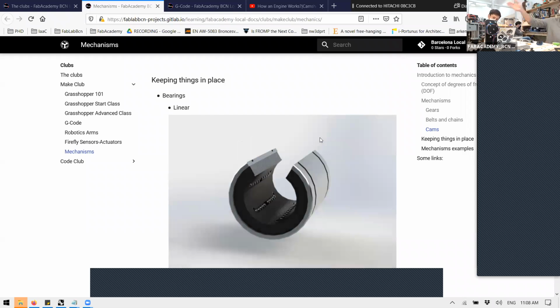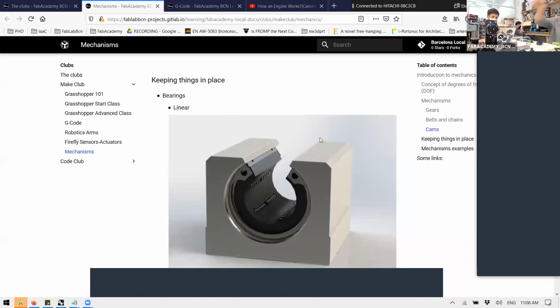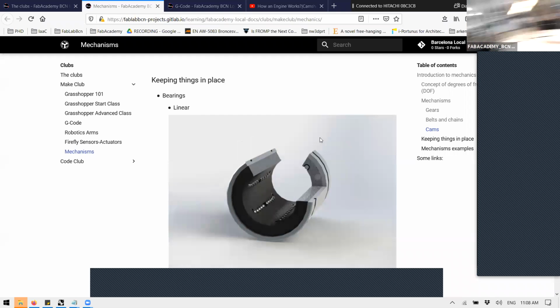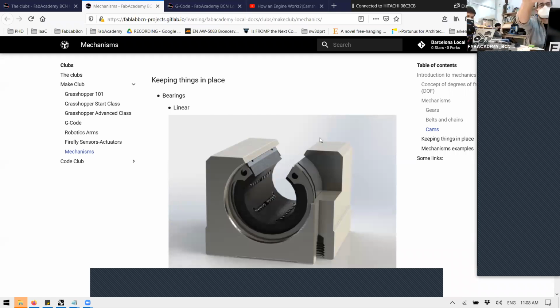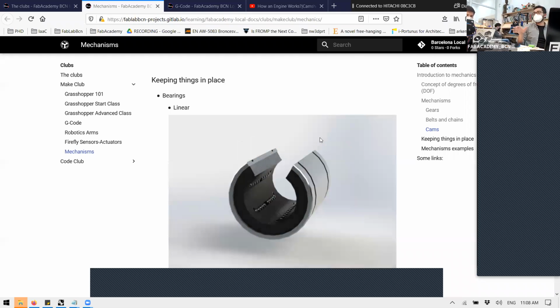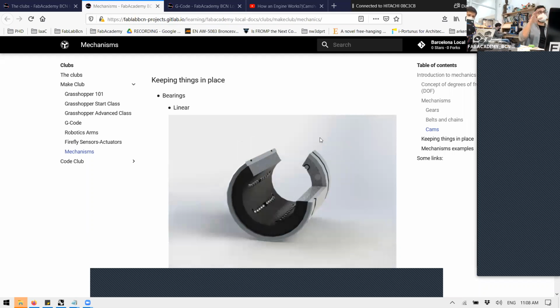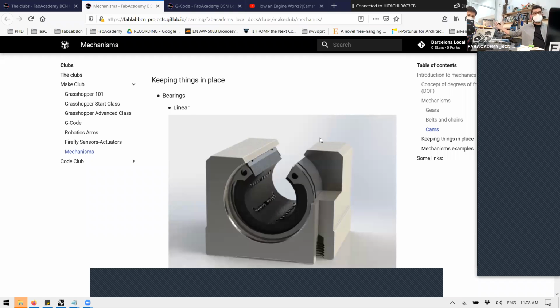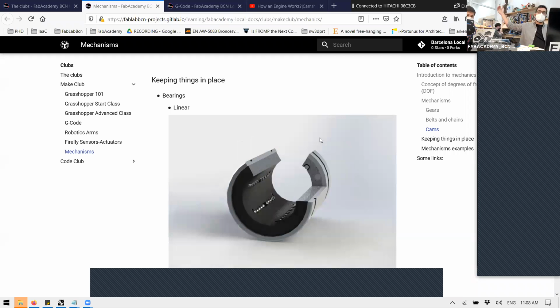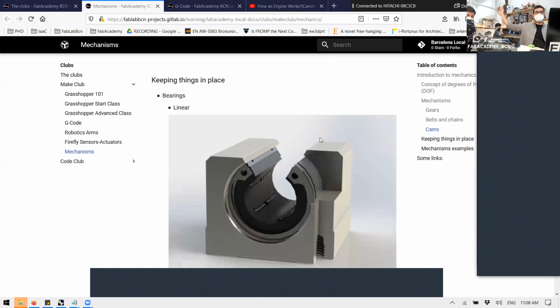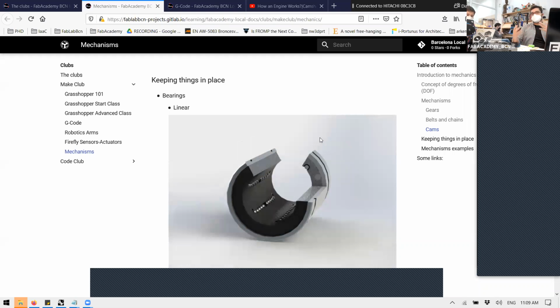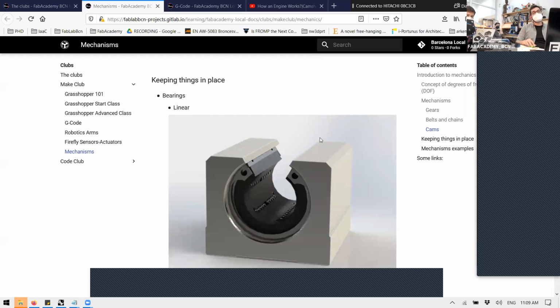For example, between that machine and that machine, the Ender 3s and the Krakens, they use the same kind of bearing, same kind of mechanism, and same kind of actuation. But just because the elements that you move are triple size, it's automatically the next motor range because you need to move more mass. And that, in general, comes by experience and by checking other designs, by reference.